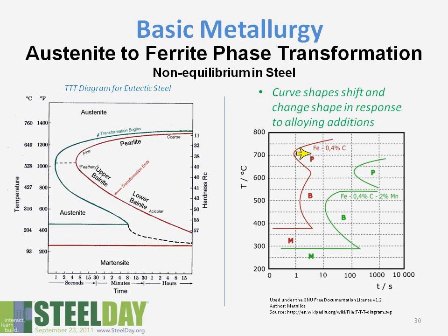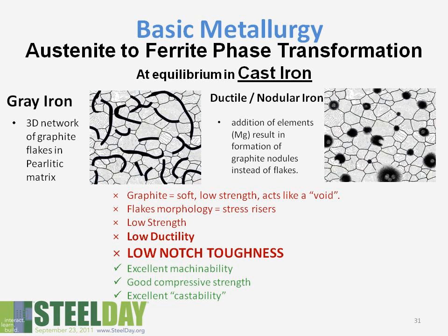For instance, here in the second curve, we see we have a 0.4% carbon steel. If we increase to 0.2% manganese, you can see that there's actually a change in the shape and position of the curves, time-wise and temperature-wise. Again, this is predictable. Again, it forms the basis of heat treatment. It's important in welding. It's important in processing. So that's the microstructures of steels.